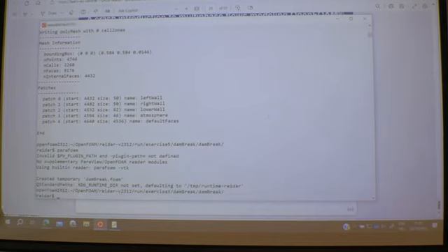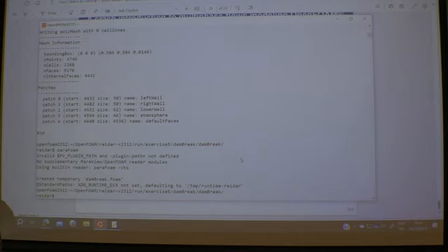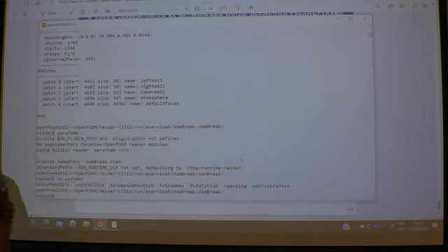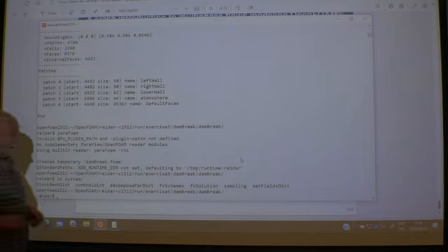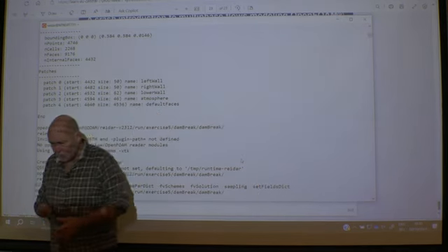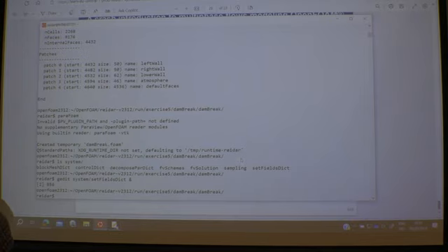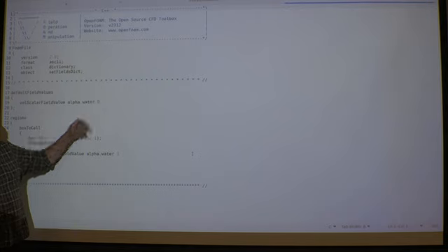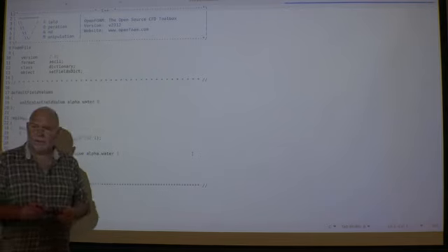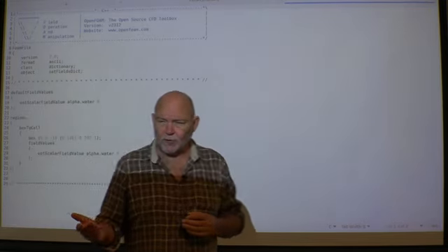And then we have this setFields thing. Inside your system folder here, you will then find a file which is called setFieldsDict. Let's have a look at that one. gedit system/setFieldsDict. And it's not a big one. So he has something that he wants to set. It's called alpha.water. Now that is this parameter that is going to be somewhere between 0 and 1.